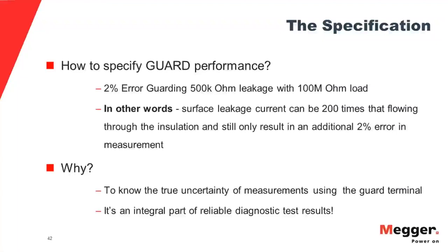And one of the areas in which they can save on design costs and manufacturing costs is on a guard terminal. So it takes a good degree of engineering to properly design a guard terminal, because this is a relatively low resistance circuit that is competing with a high resistance circuit, which is your measurement circuit. And it's competing for a limited amount of leakage current.